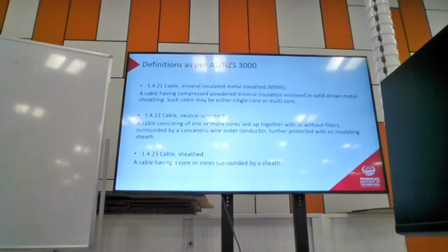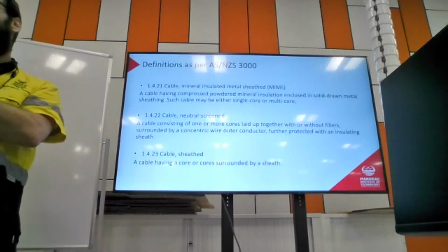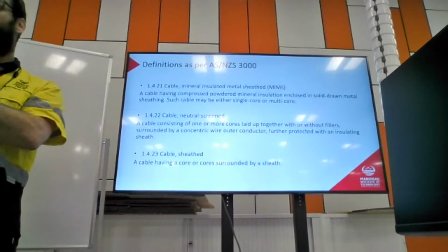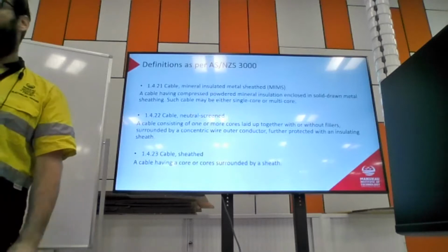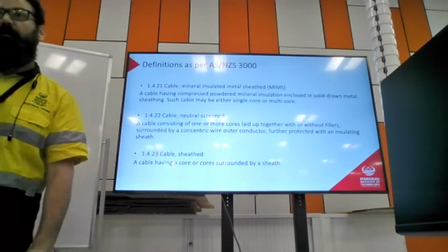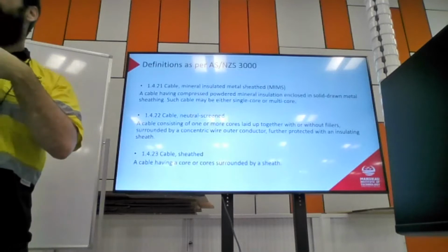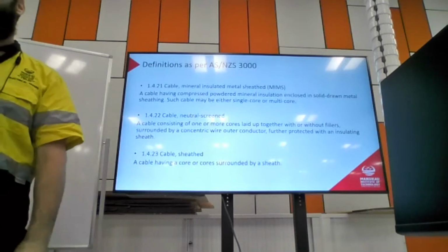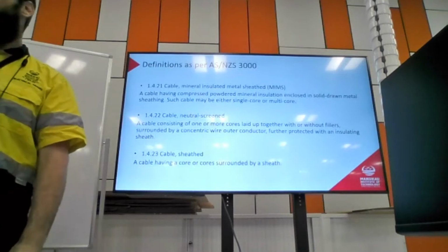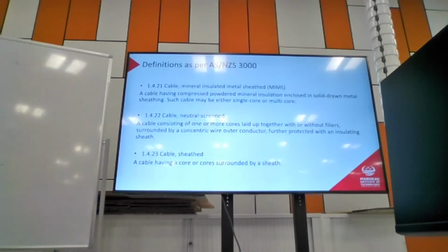What will happen is if I penetrate that cable with a digging implement, then I cannot contact the phase conductor without first contacting the neutral, which will mean I'll get a short circuit straight through the blade of my shovel, and it should blow a protective device. There's no way that I can hit the phase conductor only and then get a shock, right? So it's going to short circuit straight across the spade from phase to neutral. The spade is going to act as a short, and then it'll blow the circuit breaker. Right? Make sense? It's pretty neat, actually. I think it's pretty cool.